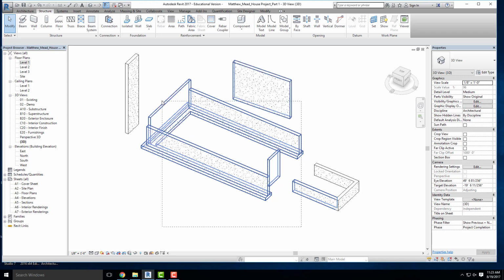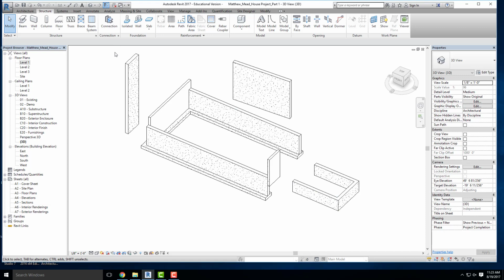As soon as that extents boundary hits this wall in the upper corner, it's now a part of that selection. Now, what's the difference by going from left to right? We'll select specific elements. Notice that as I go through this first element, it's not selecting it. It will only select it when that element is completely inside of that selection box.